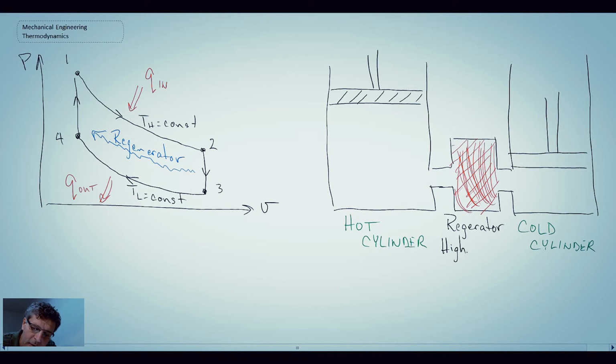So the characteristic that we would look for in the regenerator is high mass times the specific heat capacity, and we refer to mc sub p as being thermal mass. The reason why we want high thermal mass is because when the gas goes through the regenerator, we want it to exchange or deposit, I guess you could say, transfer its thermal energy to the regenerator. And then when the gas comes back the next time, we want the thermal energy to be transferred back to the gas.